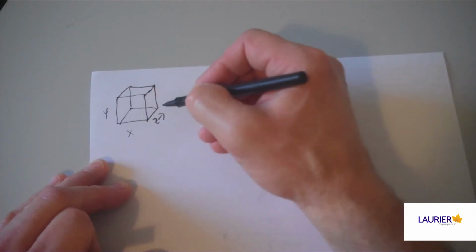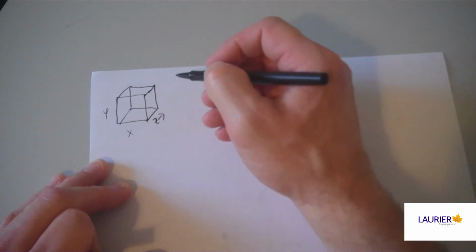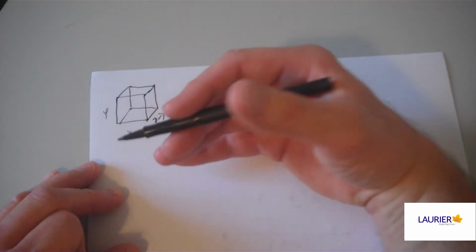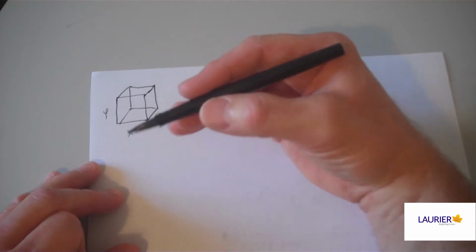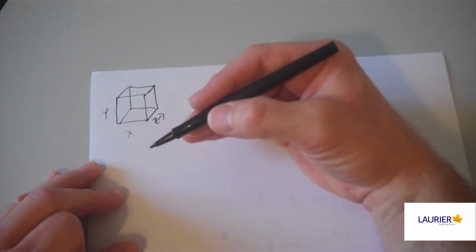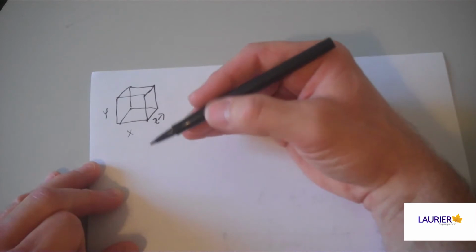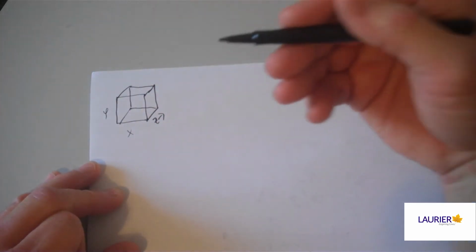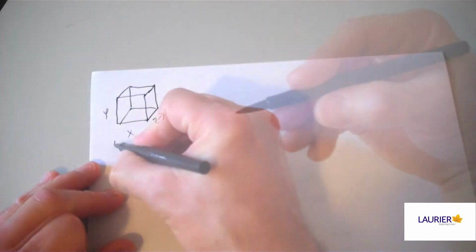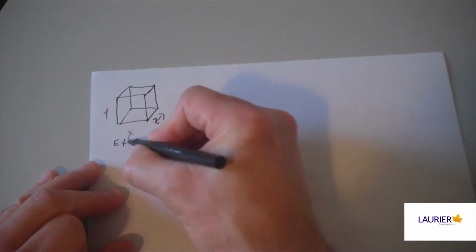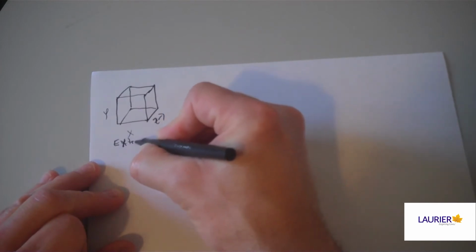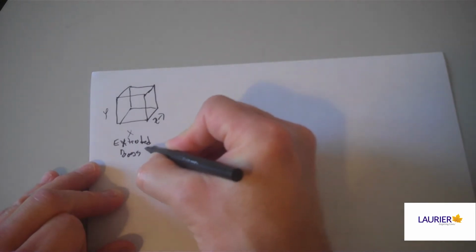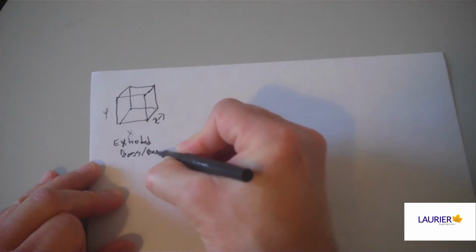When we're going to laser cut something, where all we can actually do to make something is cut straight down through a material of finite thickness, every single part that we design will use this extruded method, this normal method, straight up and down. The laser cutter is kind of a combination between a James Bond bad guy weapon and a cookie cutter. When we make a solid in this way in the CAD, it's called, not surprisingly, an extruded boss base. We'll explain what the difference between a boss and a base is in a later lesson, but for now, just remember that a boss base always adds material when it moves a contour through space.